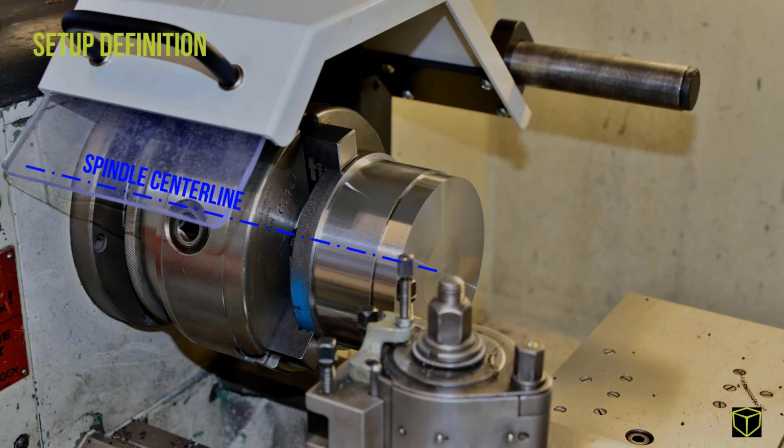Generally speaking, and following the right-hand rule, the X, Z, and Y-axis markers represent the main spindle coordinate system. In this example, the main spindle coordinate system is located from the front face of the part and along the spindle axis center line. However, this location can be adjusted to a different position. Alternate locations, such as the center of the part, or even the back face of the part and/or stock, are all valid choices. The Z-axis arrowhead points in the Z positive direction, or away from the front face of this part, and along the part's spindle centerline or axis. The X-axis arrowhead points in the X positive direction as shown.